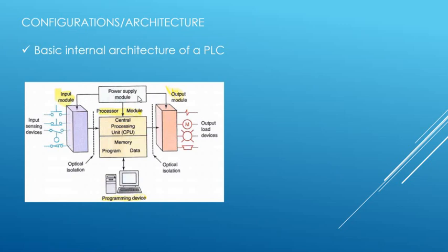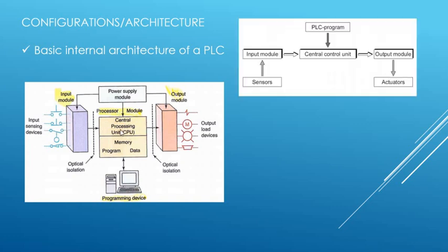So depending on what kind of PLC you're using, you might need to supply power to the module. Some of the PLC have a converter built in. Some of them don't have a converter. So you might need to supply 24 volts. Of course, there are also PLC that use 110, 220 volt AC, but most people, for safety reasons, don't really use them.